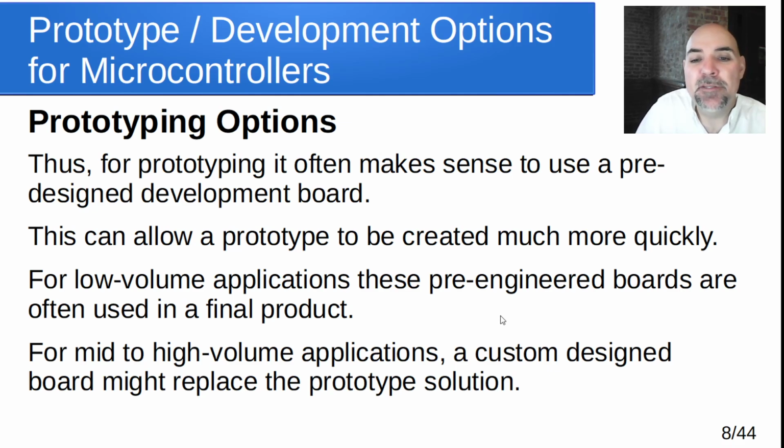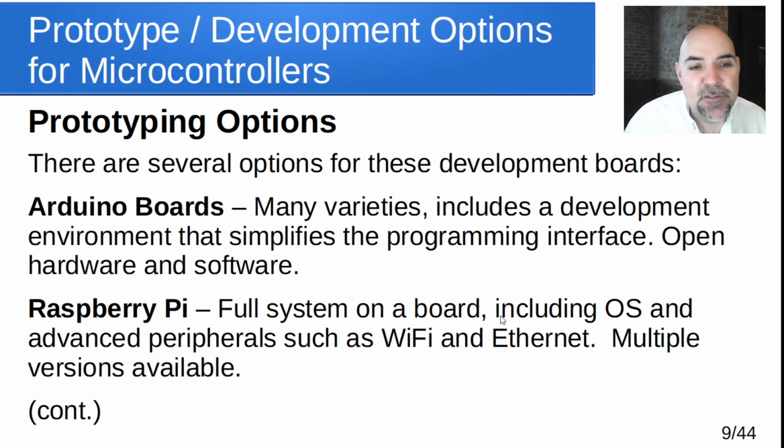Okay, so let's look at some of these pre-engineered boards. There are several options for those, and we're going to take a deeper dive into a few of them, but one of them is Arduino boards, and maybe you've already heard of those or played with those on other projects. It turns out that there are a lot of boards that are Arduino environment compatible. What Arduino is, is a development environment that you can write your code in and upload to some microcontroller target solution, some sort of board. What Arduino does a good job of is that it abstracts some of the things that you might need to learn about if you're doing it directly. For example, setting up the clocks, setting up the peripherals, how you set it up to communicate, and how you get code into it to program it.